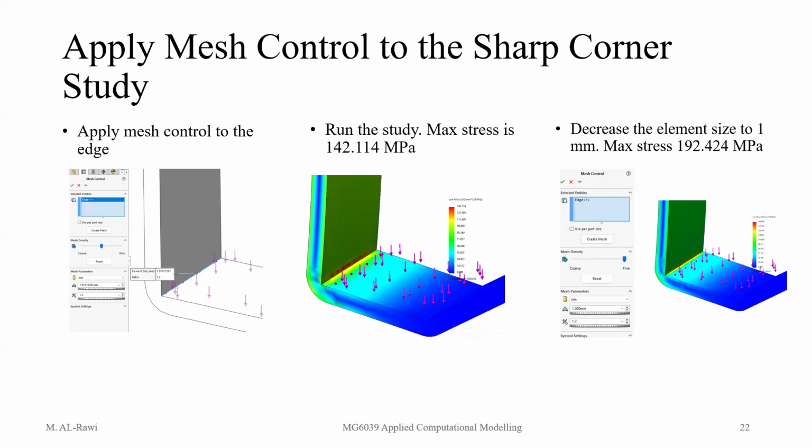When you see that triangle, it means it's not running. Now, when it's run, it will take time. You see the number has jumped really hard. So what is telling me this? It means when I don't have the fillet, I'm going to infinity. And that's inaccurate. That's wrong. That's the reason for fillets.